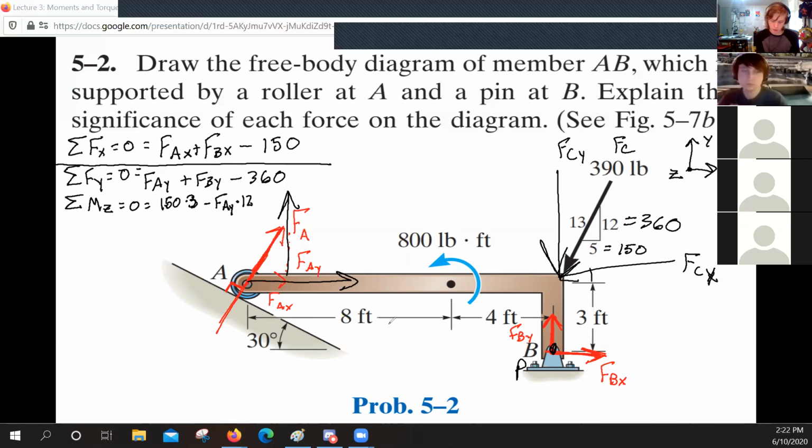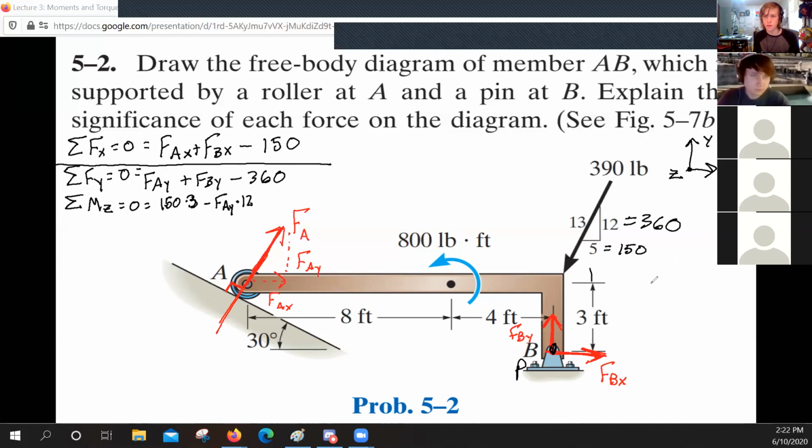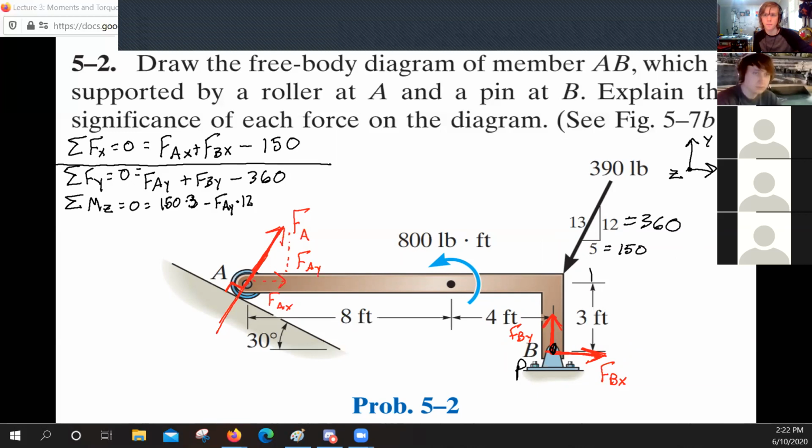And then over here, we've got two other forces. If we draw that one, keep going, it does not pass through the pivot, so we need one for that. We draw this one, keep going. It does not pass through the pivot, so we need one for that. So all these forces, if you made them super long in whatever direction they're pointing, and they don't pass through the pivot, we're going to need to put them into the moment equation, okay?